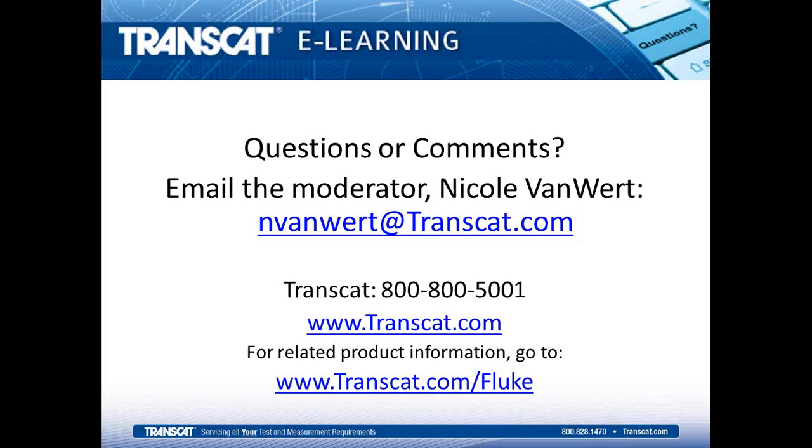So we've done a few that act like a bit of a clamshell, where you would actually split the insert in two pieces, and you would be able to put the probe in place and then close the two pieces of the insert around it, and then put it in the dry well. That's one option. The other option is to do it in a fluid to alleviate those sorts of problems, but it's typically going to be a custom insert or go to a fluid.